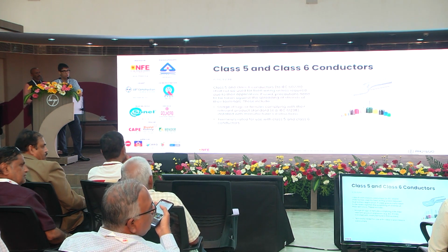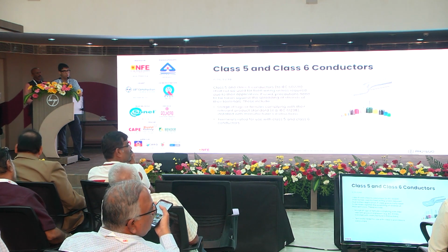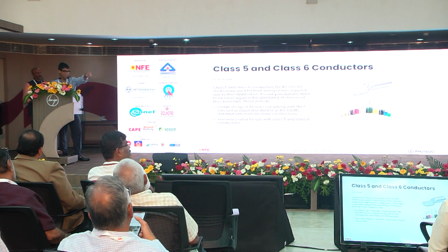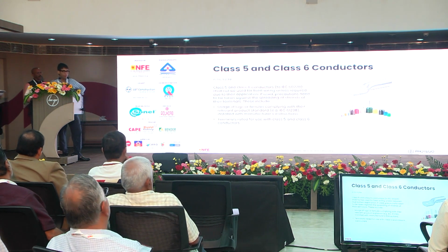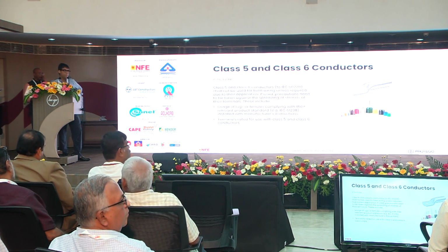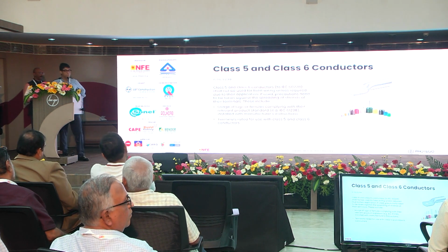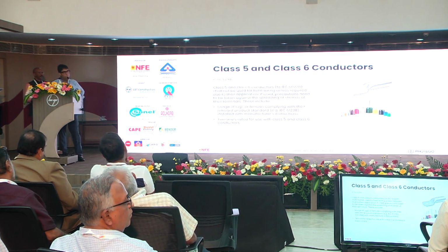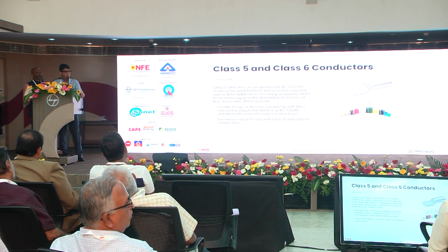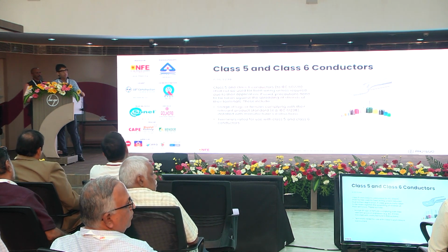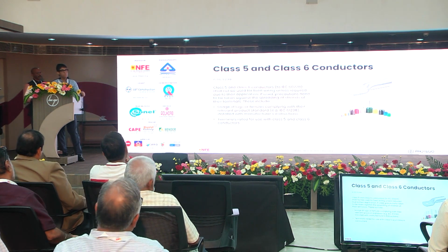Especially used for this one, shaped conductor. Shaped conductor, yes, because like I said, the shape of the conductor is very important. Many times the problem is that when you use a connector or lug, 100% surface to surface touching is not there. So this is specifically developed for the shaped conductor and can be used successfully.